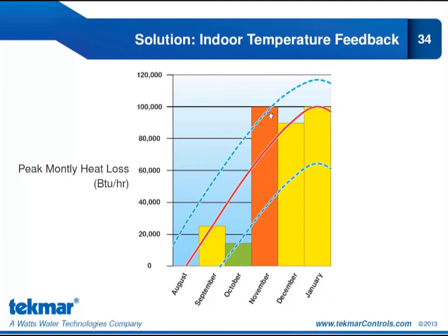And so the automatic shifting of the reset curve depending on feedback from the zones is what allows us to have more fine-tuning of our system. It allows us to reduce our supply water temperatures wherever we can, but still provide the comfort that occupants demand. We are not compromising on comfort, we're actually increasing comfort because we're matching the heat delivery to the actual heat loss of the space.